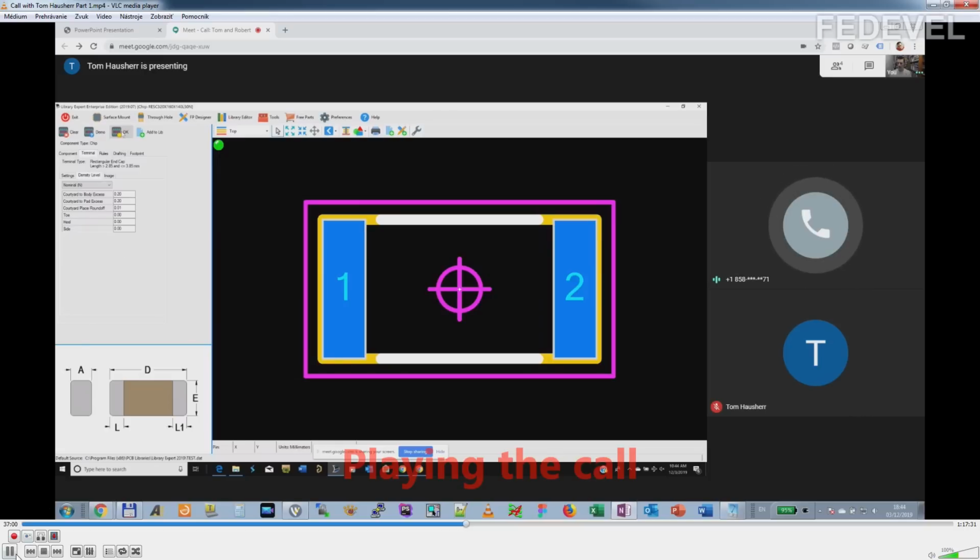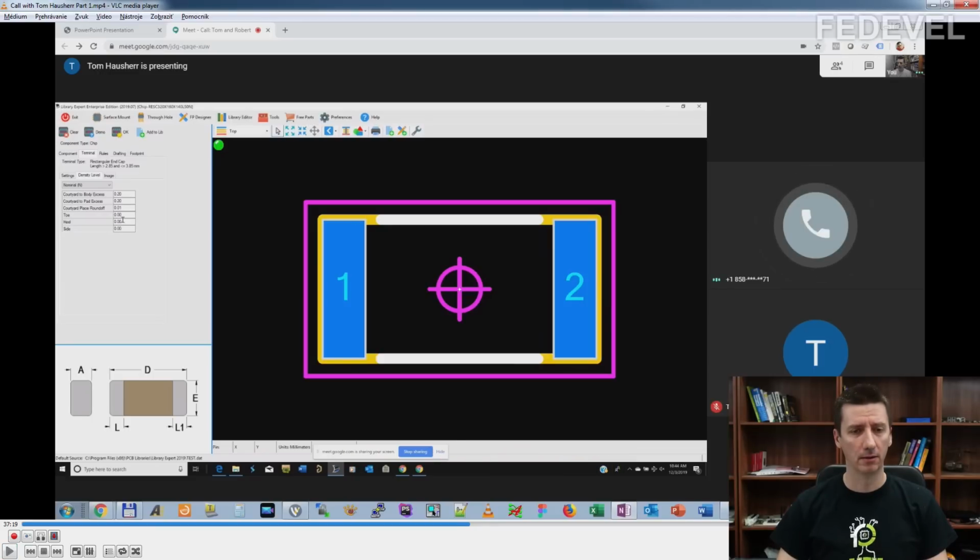So whenever we're going to generate a pad, we ask, okay, what's the nominal lead? Then make the pad size the same size, X and Y, okay? And then we add the toe, heel, and side values right here, okay? And then we add the fabrication and assembly tolerance. Wait, what? Tolerance?